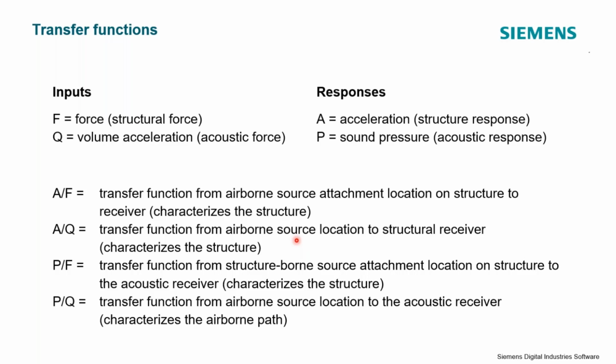Similarly, there's also this P over Q, where I'm measuring an acoustic response from an acoustic force. So I just want to know the transfer function, fully airborne. A over F, structure-borne transfer function. A over Q, airborne, structure-borne. P over F, airborne, structure-borne. P over Q, simply just airborne.